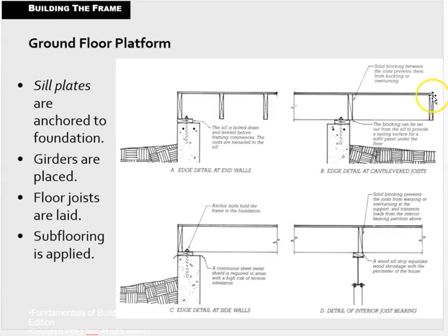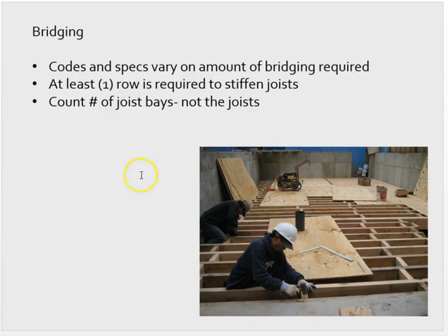And here is a structural rim board at the end, a continuous structural board, and it has an X through it. And this is blocking, that is only running from this joist to the next joist closer to us, and it is not continuous, and we know that because there's only a single line going through it. So structural rim board, non-continuous blocking, structural joists, structural rim board, structural sill plate, again another sill plate on top of an I-beam, and then this would be blocking sitting over the beam. Okay, and then subflooring is applied, and I think we're almost out of the platform here.